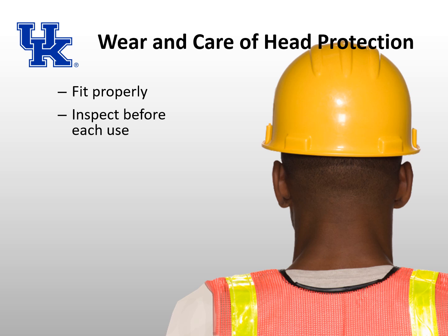Inspect the hat before each use. Check for cracks or any other damage that might reduce the ability of the hard hat to provide protection. This includes inspecting the suspension system for cracks, worn straps, or other damage. Make sure the suspension system is installed properly and not backwards.